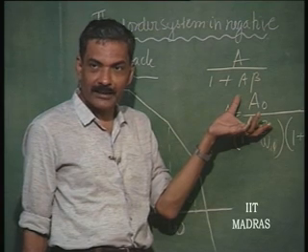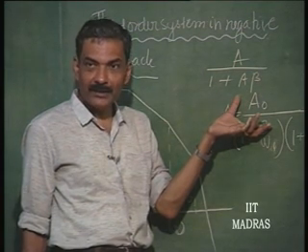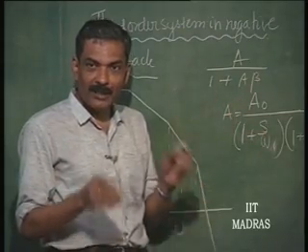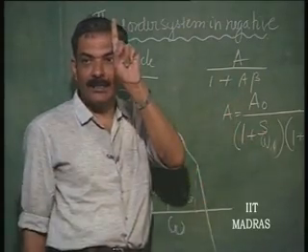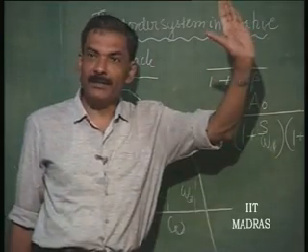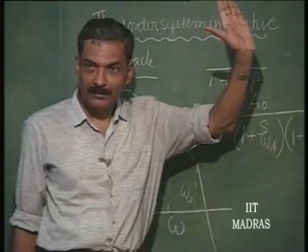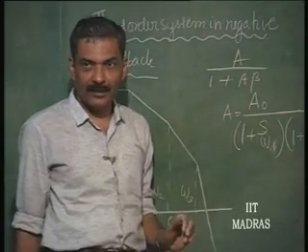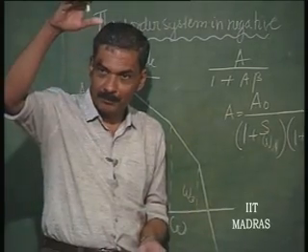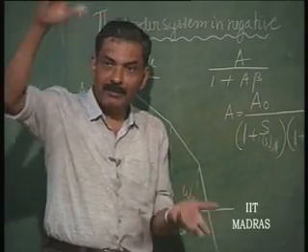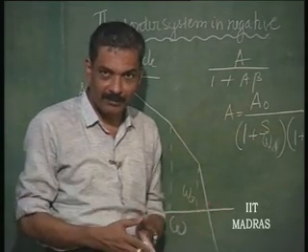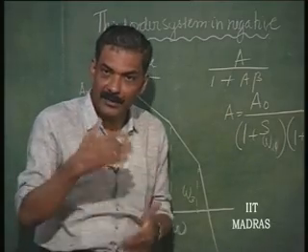For an oscillator also we had the same thing. The only difference was, in the case of an oscillator, the loop gain A beta was becoming equal to 1 only at a single frequency, whereas here beyond that frequency, if it is greater than 1, it can sustain oscillation at higher frequencies corresponding to that, and oscillation may keep on building up. It will be a square wave instead of a sine wave at that particular frequency. The amplitude may be unlimited, or it may get limited by the nonlinearity of the amplifier.